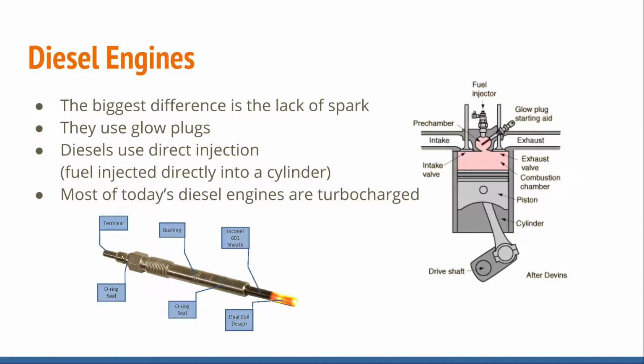So how does this engine run without a spark plug? Well, it works the same exact way as a gasoline engine as far as the pistons and the valves, you know, the 4 strokes. But the air fuel it brings in, diesel fuel obviously is more of an oil than gasoline. But when the piston compresses the air fuel mixture, a diesel engine uses a lot higher compression rate than gasoline engines. So as that air fuel is getting compressed, it's actually heating up. It actually gets really hot just by the compression.